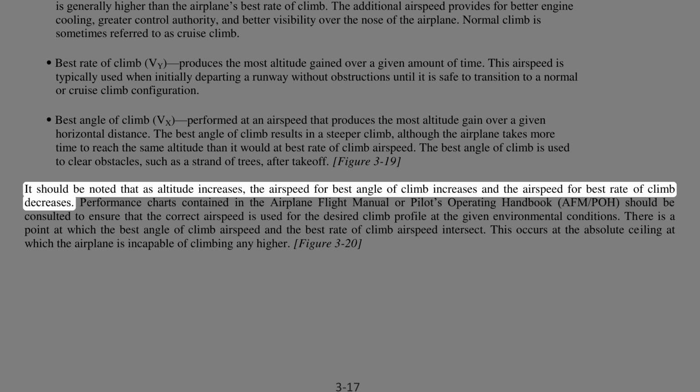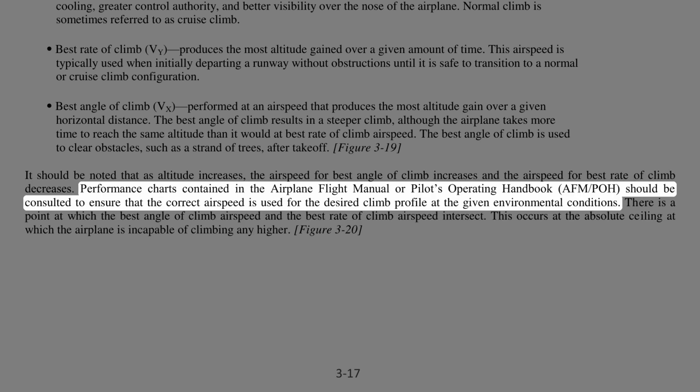It should be noted that as altitude increases, the airspeed for best angle of climb increases and the airspeed for best rate of climb decreases. Performance charts contained in the Airplane Flight Manual or Pilot's Operating Handbook, AFM/POH, should be consulted to ensure that the correct airspeed is used for the desired climb profile at the given environmental conditions.